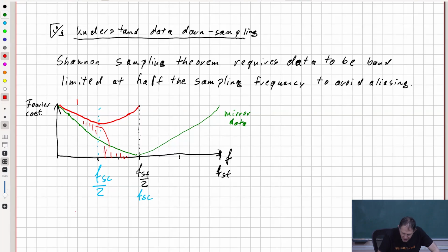And this will be the apparent. This is not the right signal, but this is the apparent signal. With our aliasing problem. So this happens if you undersample your signal. Yeah? So this means that something that should be actually high frequency, but what does not fit into your sampling will turn out to be of low frequency.